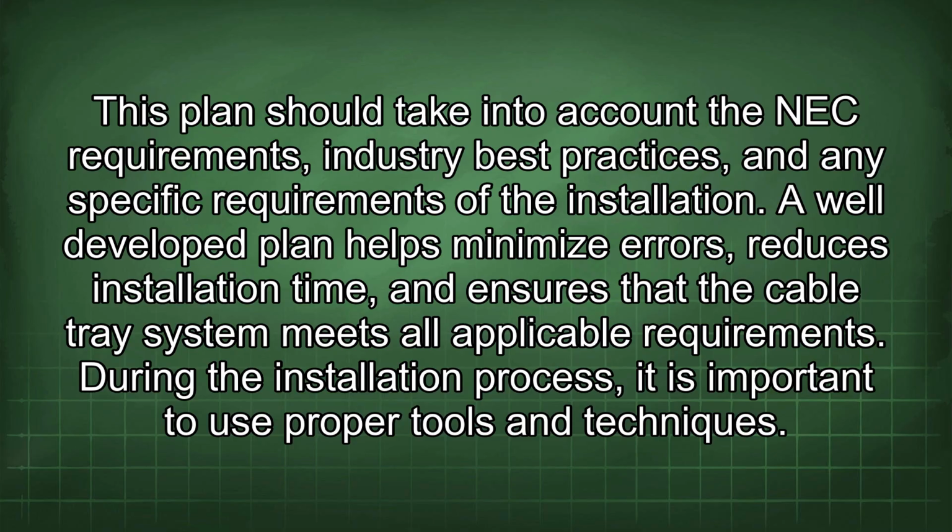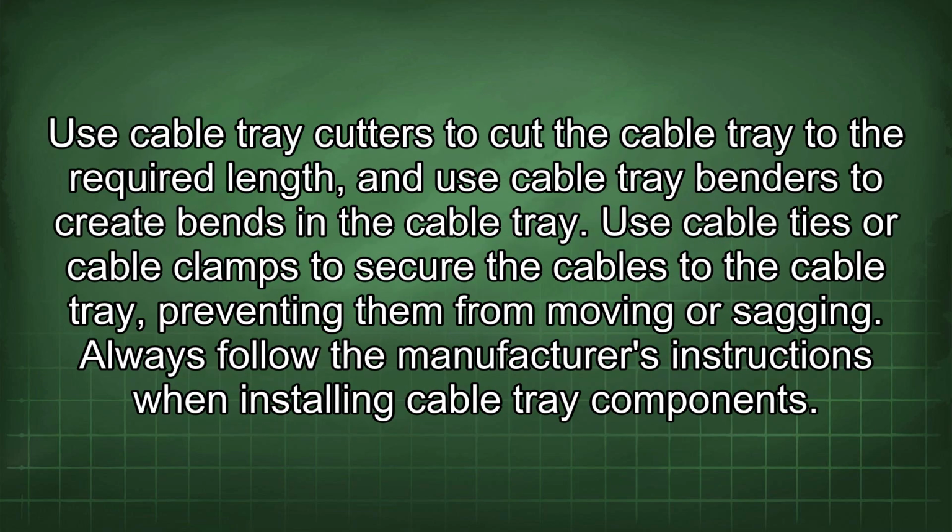During the installation process, it is important to use proper tools and techniques. Use cable tray cutters to cut the cable tray to the required length, and use cable tray benders to create bends in the cable tray.